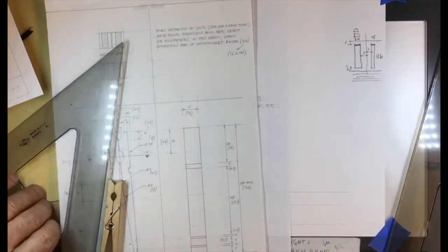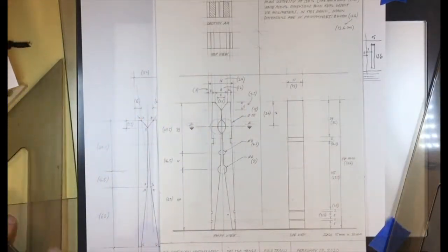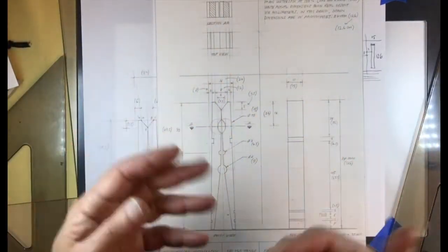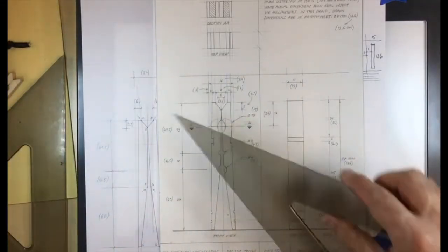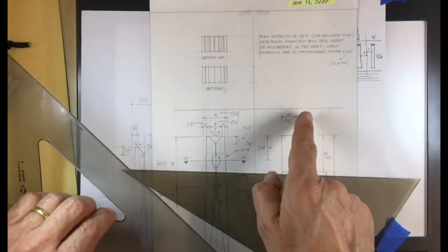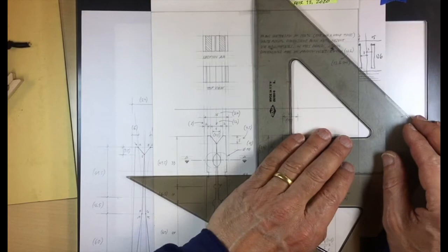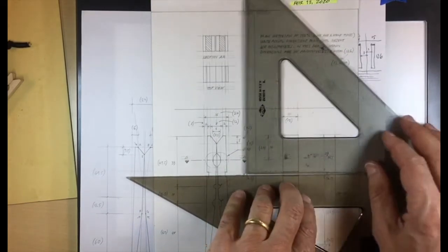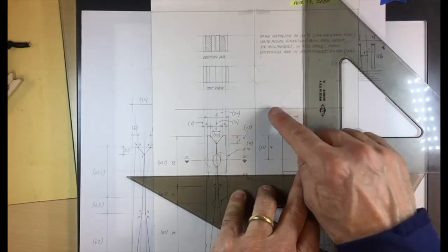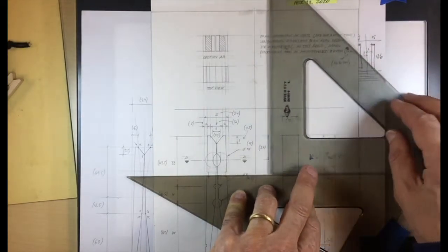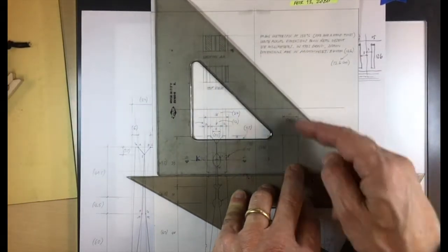It doesn't matter that much, but if we wanted to be strict about the construction, this is how it would be done. What happened here is that I transferred these lines to get the top view by using my 45, okay? First I project these lines up, and where they hit that plane, I project them with that rotation. I do that by using the 45, which gets me exactly the same height.